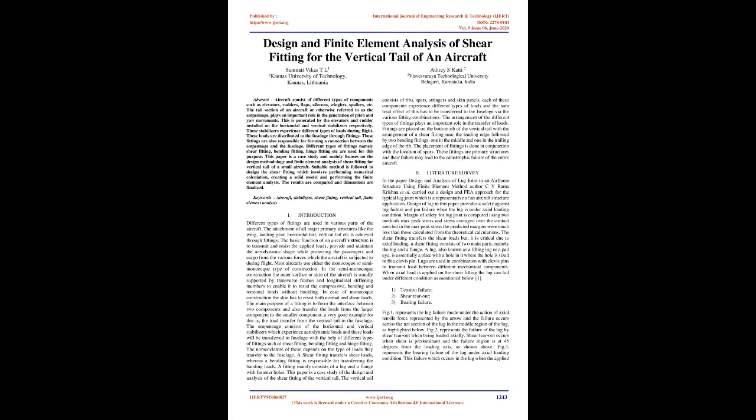These loads are distributed to the fuselage through fittings. These fittings are also responsible for forming a connection between the empennage and the fuselage. Different types of fittings, namely shear fitting, bending fitting, hinge fitting, etc., are used for this purpose.